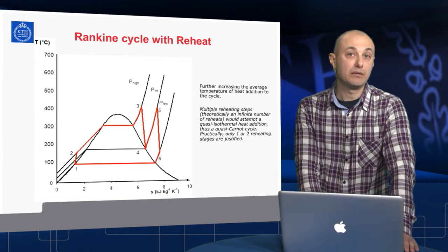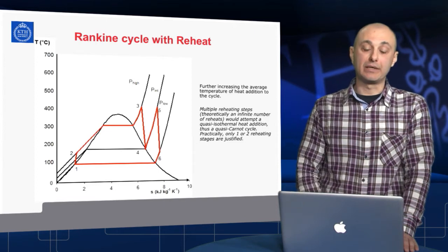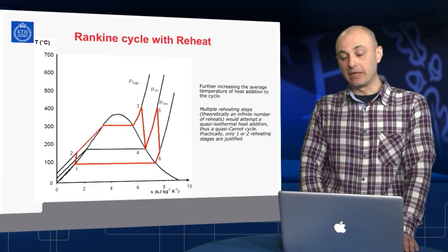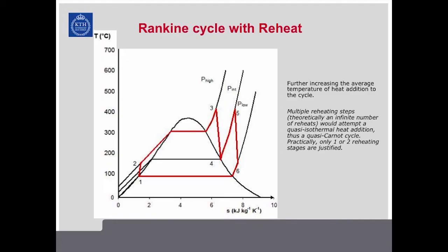Reheat is one further step that we can add to the common steam cycle, converting it into something that has a higher potential, again, for conversion of heat into power. It is the same Rankine cycle, and today we usually refer to a Rankine cycle as any generic vapor cycle for power generation. If we add reheat to it, that would be simply a second superheating step.